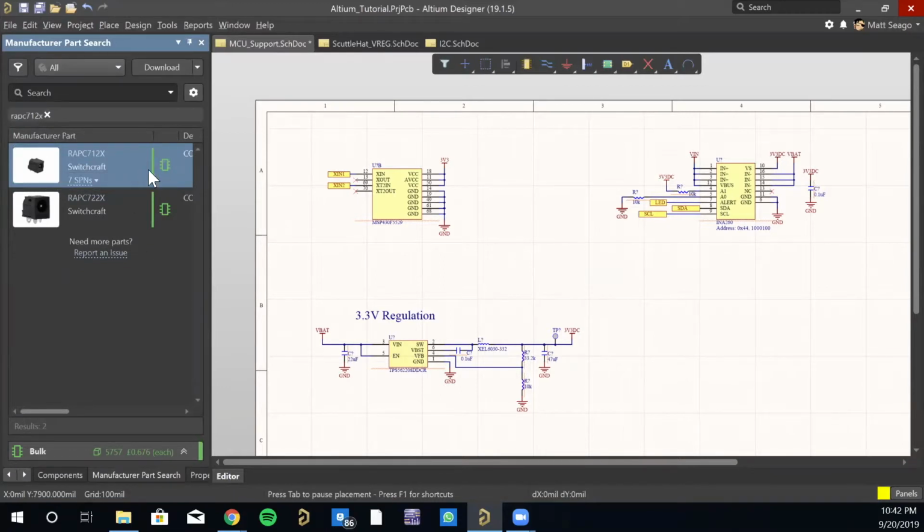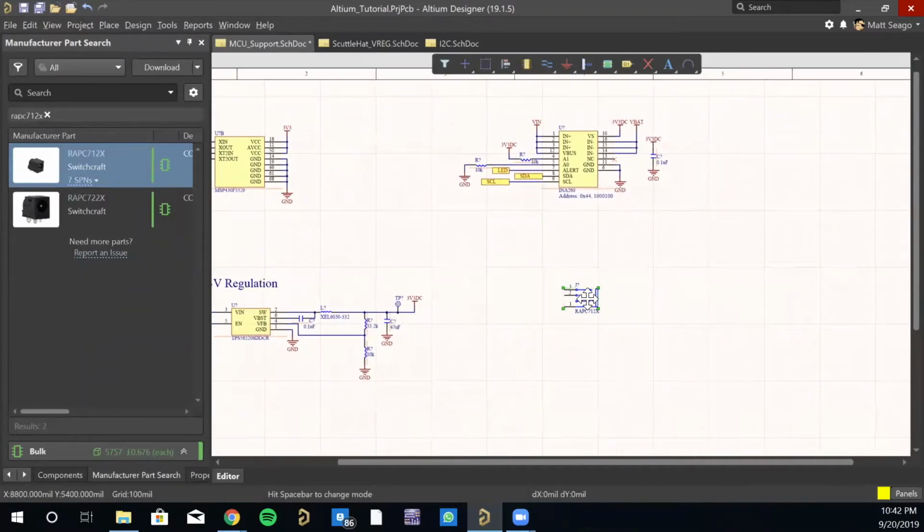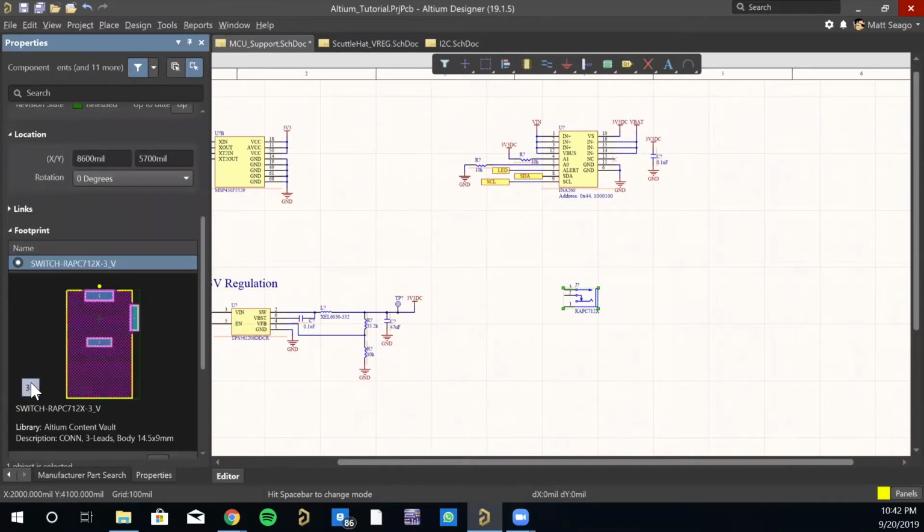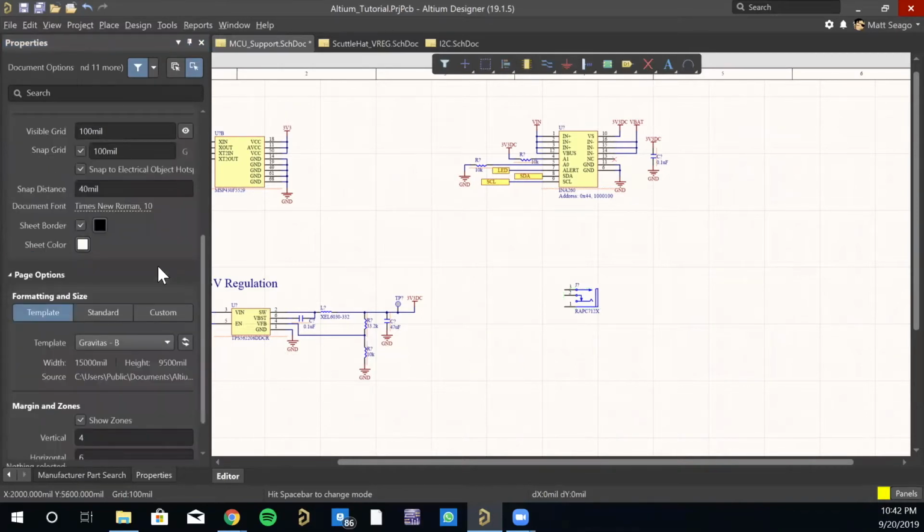And because everything's green here, I can drag it over and it shows up in my schematic. And so there's that. And we do get a footprint for it. So that's pretty cool. Now, I wouldn't count on those 100% working every single time, but it's usually pretty safe, and we can always do that paper test. You can always do a paper test with connectors.